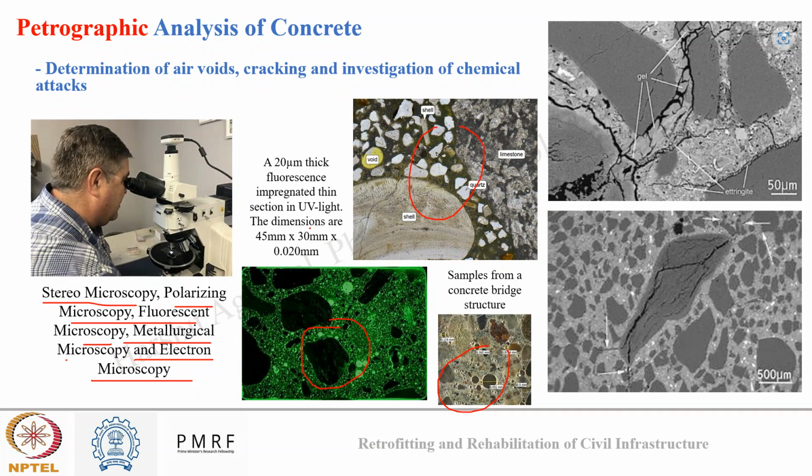One for detecting voids and segregating different components of a sample collected from a concrete bridge. So here you can see we collected a sample from a concrete bridge, and we are detecting different voids and segregation that occurred. Okay. And the fluorescent one shows how a thin film concrete sample appears under microscopy, and which can give us information related to interfacial transition zone and aggregate cement distribution. While here also you can see voids and different phases were discovered from the sample collected from one field.